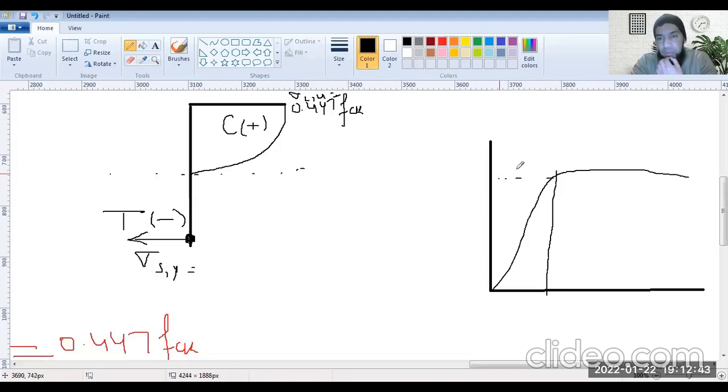So there you will have the maximum stress as sigma sy, but this is again the characteristic curve of our steel. There is no problem in terms of steel, that there is a shape factor, because steel is manufactured in factories. So there are hardly any issues with the shape factor. There is hardly any issue with the workmanship. Steel bars are of the same size and length, so no issues with the shape factor, no issues with the uncertainty dealing with workmanship.